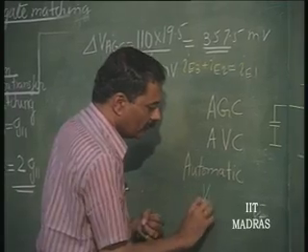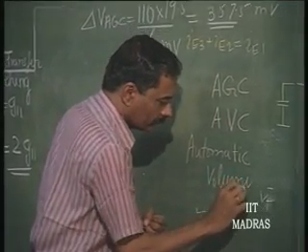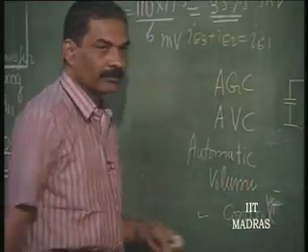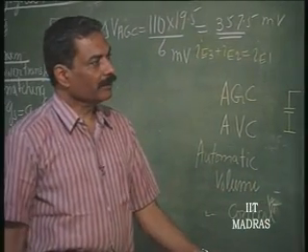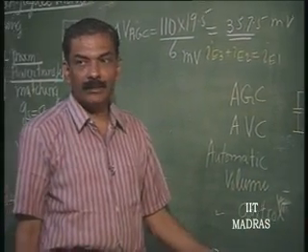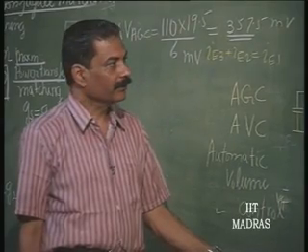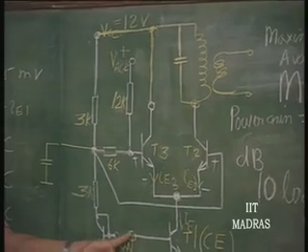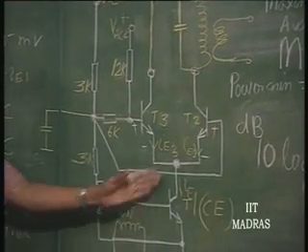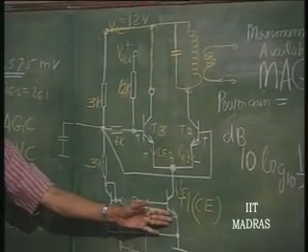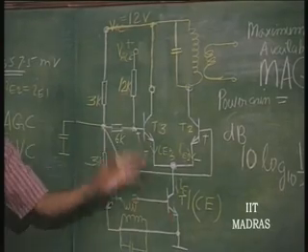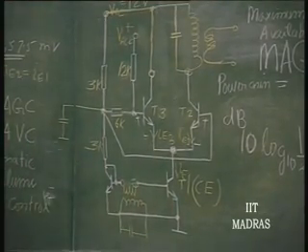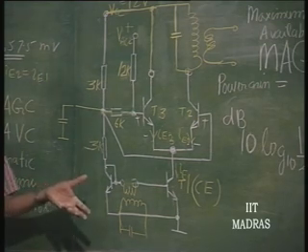Automatic volume control or gain control. So, you will see that this is a must in all receiver design, and that is very conveniently applied here, so that your parameters Y11 and Y21 do not vary, because this current remains constant. In a regular Cascode structure without this arrangement, these parameters vary and this gain also varies, because AGC is necessary,